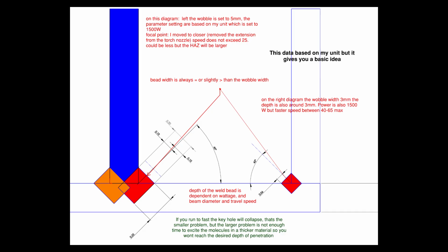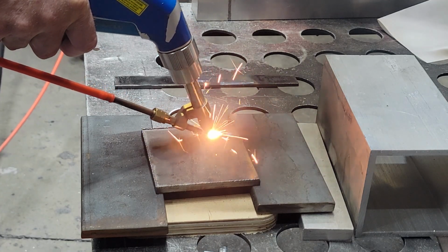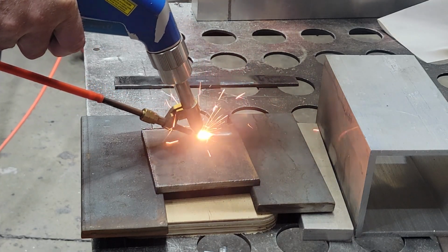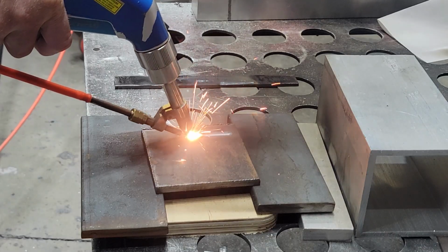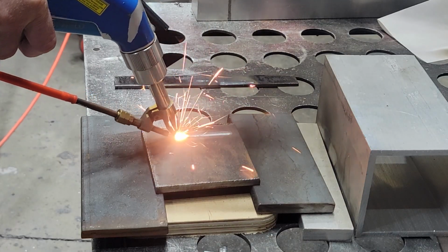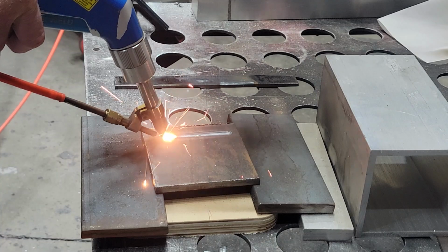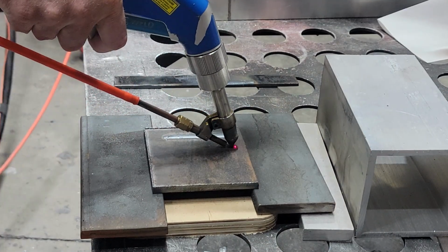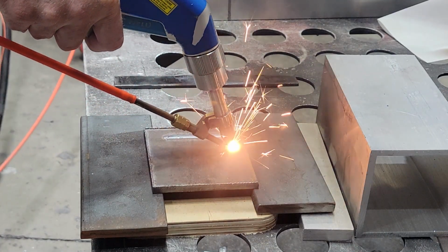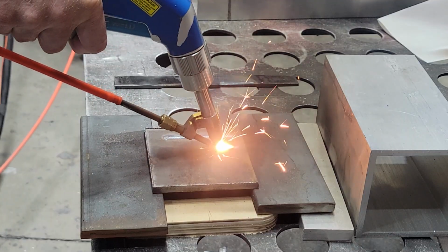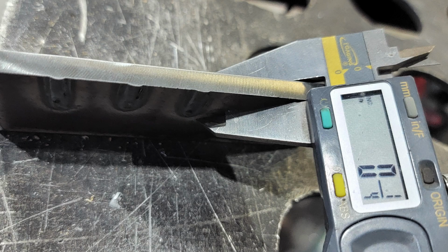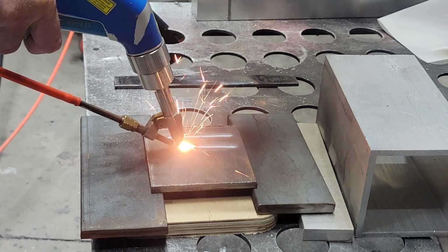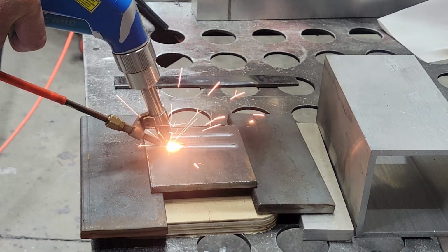Laser welding demonstrates this principle with even greater clarity. For example, the IPG LightWeld 1500 is rated for approximately 4 mm penetration under standard parameters. However, controlled field testing has shown that full penetration of 0.25 inch, 6.35 mm, can be achieved in a single pass when the two pieces of material are properly fitted with minimal gap.